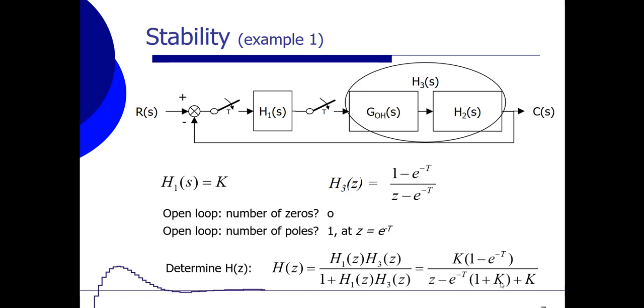And now we are going to use the rules of the root locus in order to see how my pole, because we have only one pole, moves as a function of an increasing K, so when K increases from 0 to infinity. In that case, we can see what the pole locations will be, in what case this system is stable, and in what case this system is unstable.